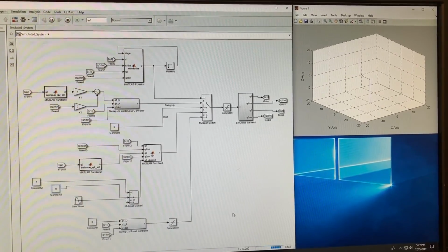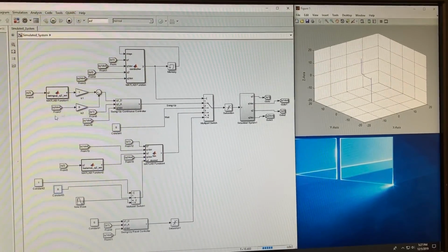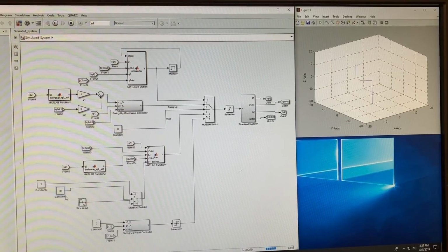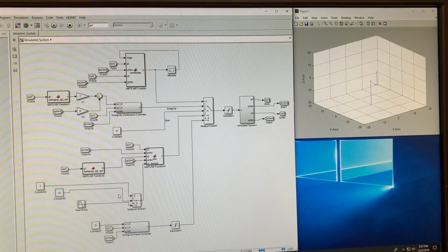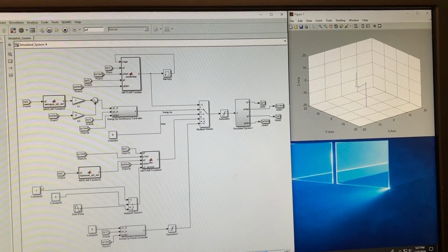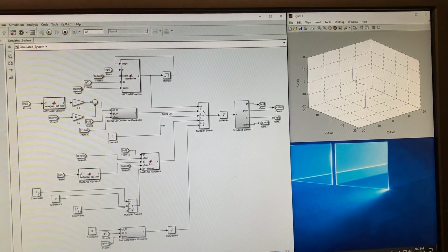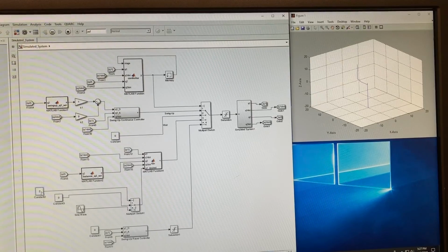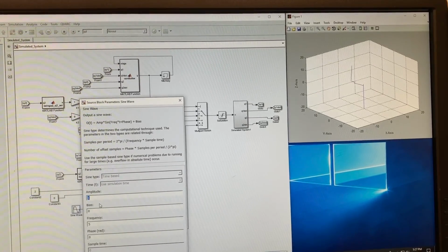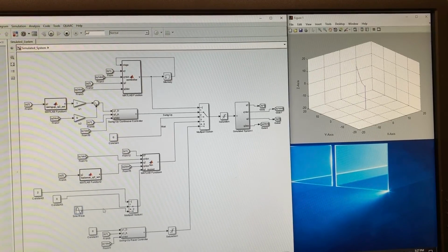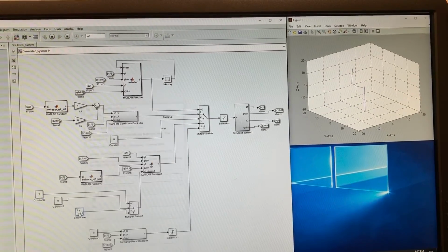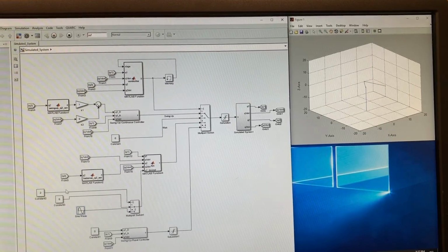The position reset stage is activated when the balanced pendulum is knocked over due to exceeding the threshold that the motor could balance the linkage. We set this to be plus or minus 25 degrees so that the system is more robust in trying to remain balanced. The wait stage is activated after the system has been knocked out of balance and it resets it to its starting position of 0. The wait stage provides 0 voltage to the motor to allow the system's energy to disperse before being kicked into the swing up stage to resume.